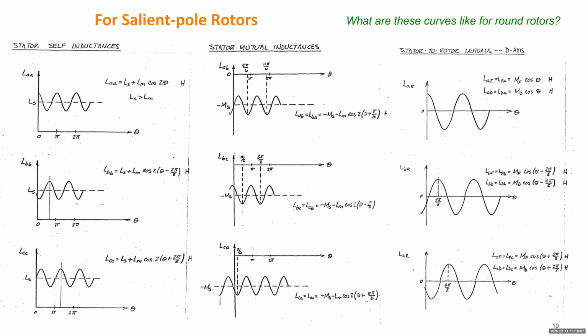For this case, permeance is a constant. But the coupling between the two windings, one on the stator, one on the rotor, still changes periodically by 360 degrees. So those will be the same even for the round rotor generator. That's why some research just uses round rotor generators, even though it has one additional winding, because they make a lot of things easier. So at least those inductances will be almost constant. Only those three will be theta dependent.